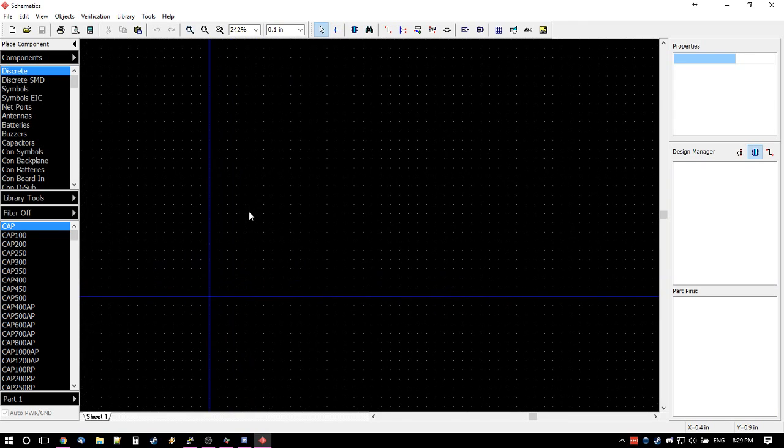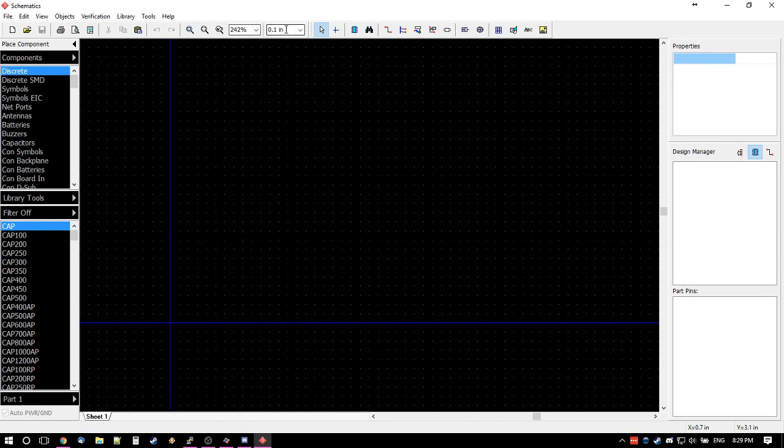Another oddity of the PCB industry is that we're still sort of stuck in half metric, half imperial, which is really annoying. Anything that's a through hole part, which means that the pins of the part actually go through the PCB, they're measured in inches, and anything that's surface mount, so parts that are soldered directly to the surface of the PCB, they're measured in millimeters typically. This gets really frustrating, but since we're going to be working with through-hole parts only, we don't need to worry about it. So you can set your grid to either 0.05 or 0.1 inch to start.